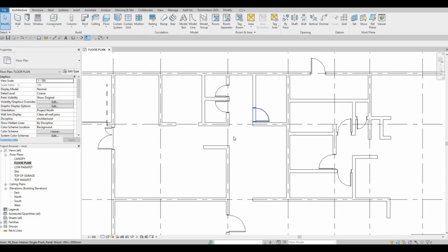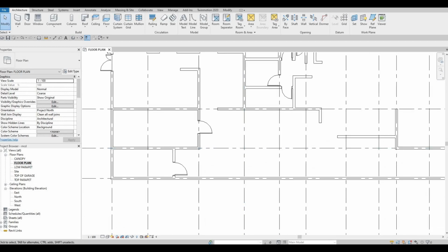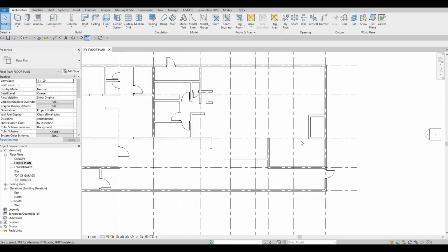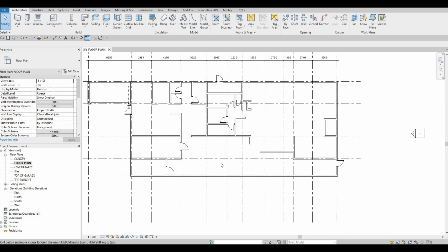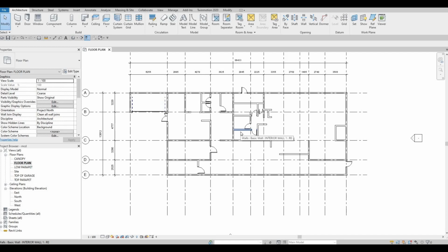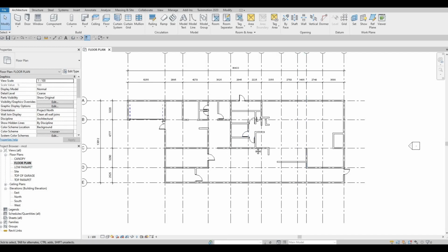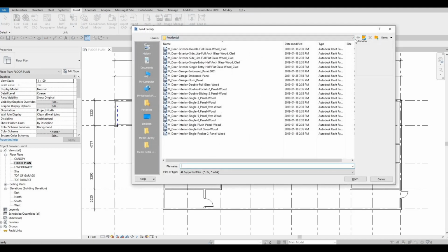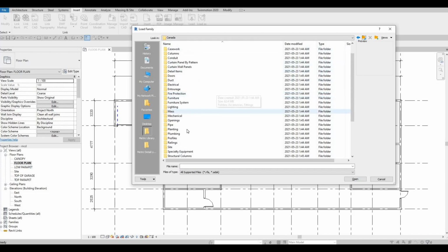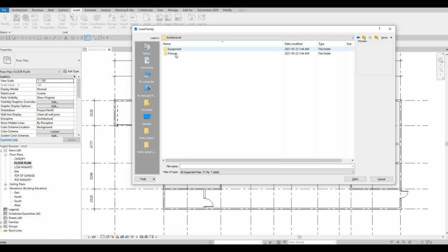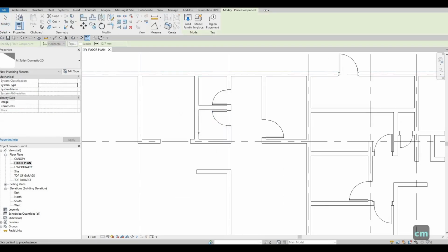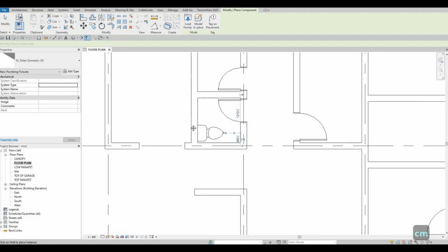And then what we can do here, I'm just double checking if we have all the washroom doors and all the doors that we needed to. So here we can have it differently. I think we're good in terms of what we can add here. Maybe we could add in the toilet so that everybody will know where the toilet is. So go to plumbing, architecture, fixtures, and then water closet. Let's add toilet 2D instead. We don't need 3D for now. CM. So let's add in the toilet right here and right here.